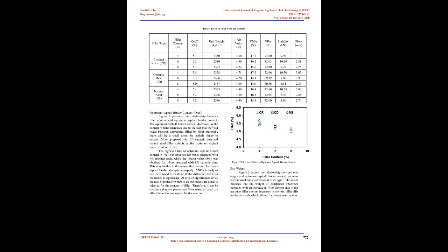See test program. Marshall test specimens were prepared using different types of mix separately according to the selected aggregate grading for 4% to 6% asphalt binder content. The specimens were subjected to Marshall stability and flow test as per AASHTO T245-82. The cylindrical specimens were then compressed on the lateral surface at a constant rate of 2 in/min, 50.8 mm/min, until the maximum load, failure, is reached. The load resistance and the corresponding flow value were recorded. Volumetric analysis was made for each series of test specimens after the completion of tests.